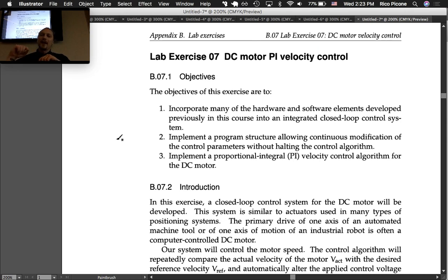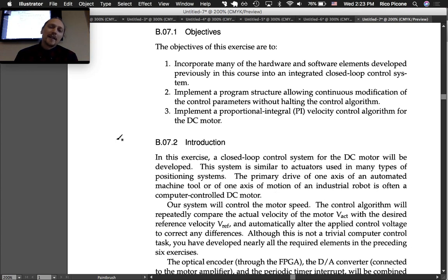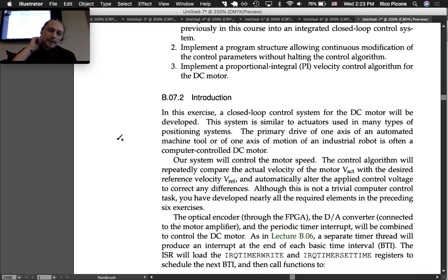Essentially, what this is describing is what transfer function you want to have that the MyRIO behave like. So you know how last week in Lab 6, we learned how to make it behave like a very specific filter. Well, that filter is going to be a PI controller transfer function. And you don't have to actually derive it. I kind of give the transfer function to you. So we'll get into it. It's pretty cool.